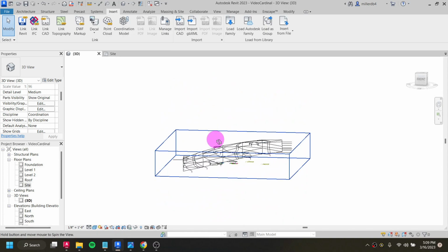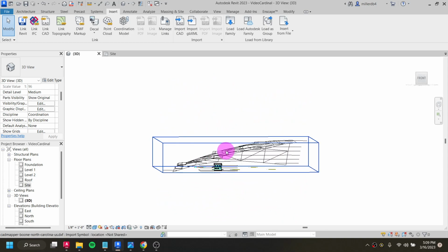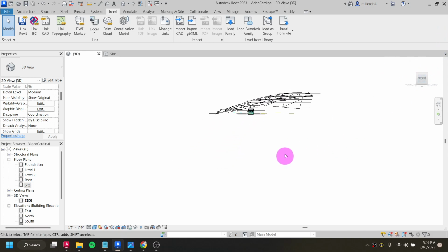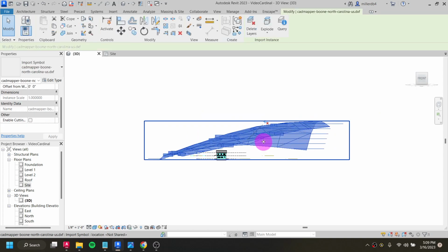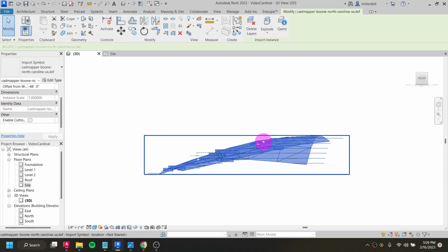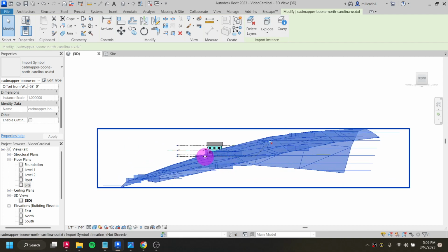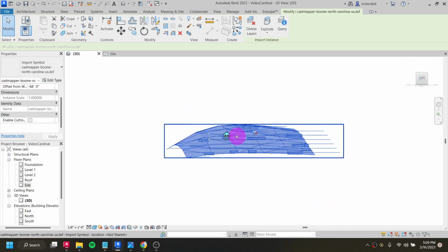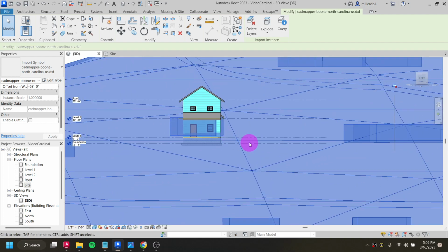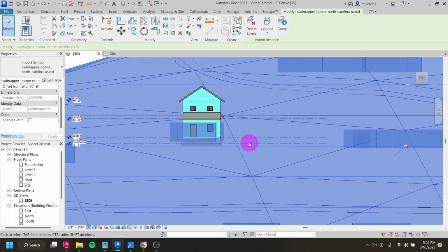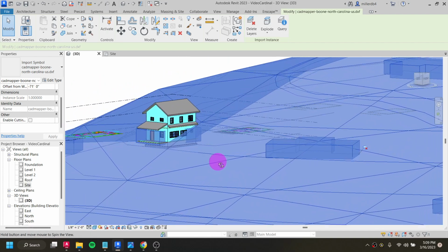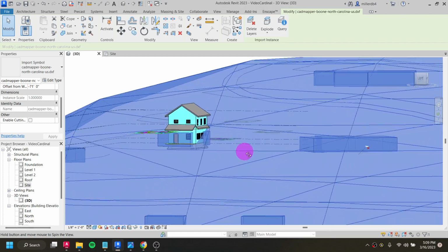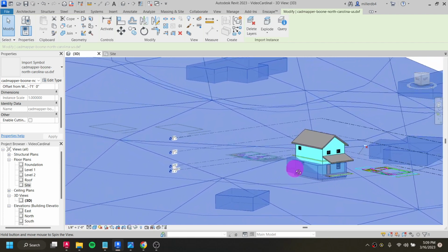However, I have the problem of it's sitting way above my building. What I'm going to do then is I'm going to click on front, and I'm going to click on this, and I'm just going to use my arrow key just to kind of shuffle it down. I'm just going to eyeball it from a couple of different angles so that the site is sitting pretty well with the ground, which is going to be a little hard to do since we're on this steep, steep hill.